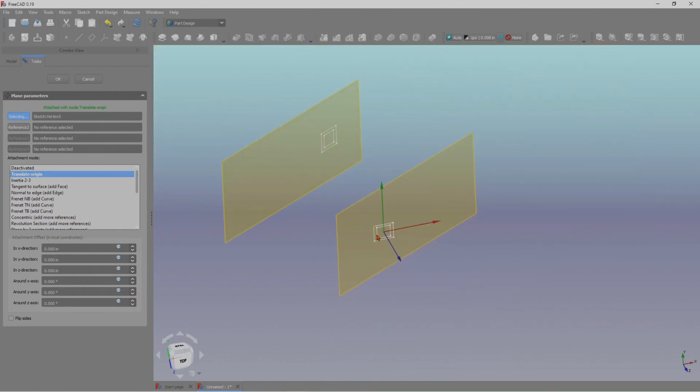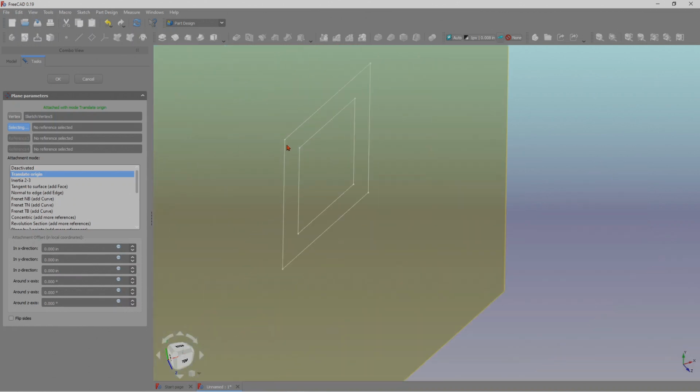Now it became interesting, right? So it went to sketch, which is the first sketch, and selected this vertex, which is vertex 5. Now I want to do this second reference point. So you can do multiple reference points. I want to create a second reference point, and I want to pick this point. Once it gets highlighted in yellow, pick that one.